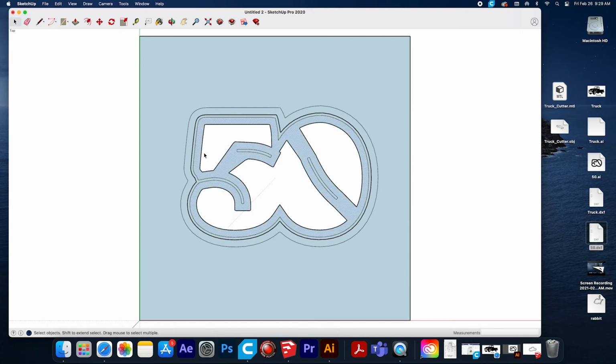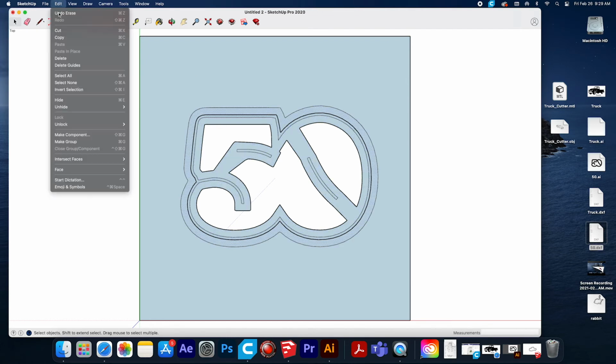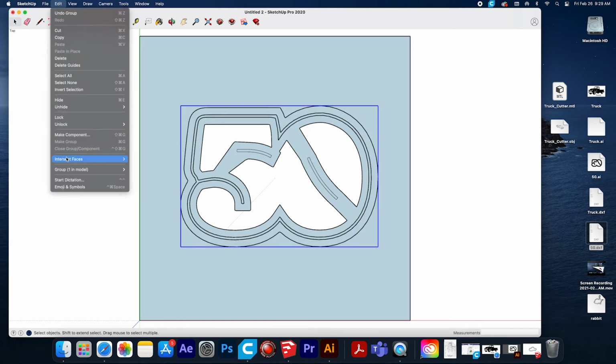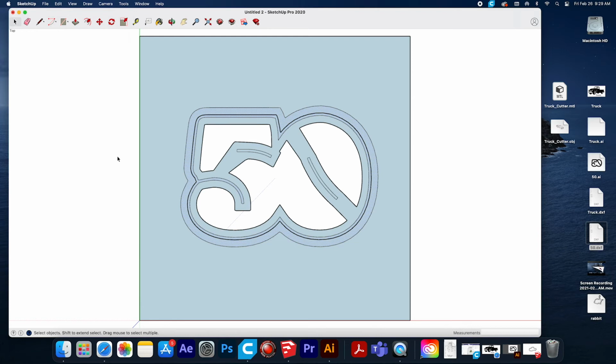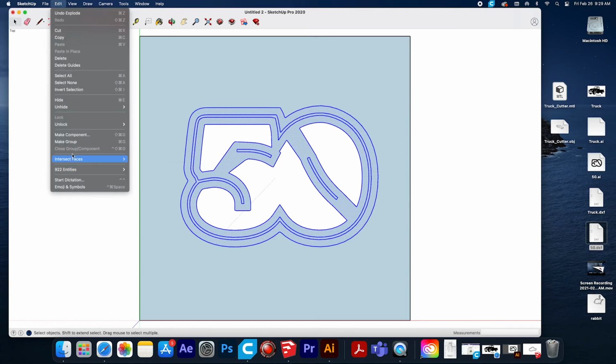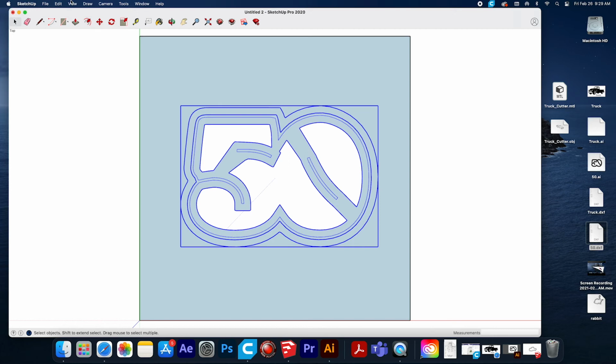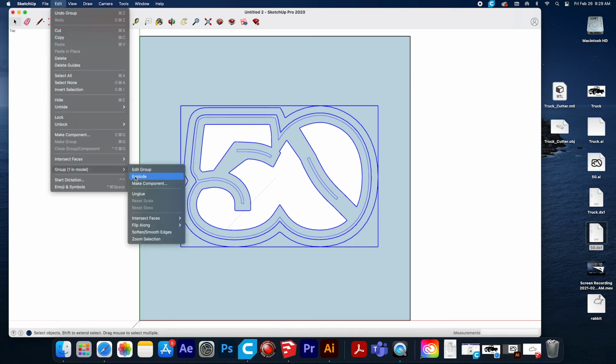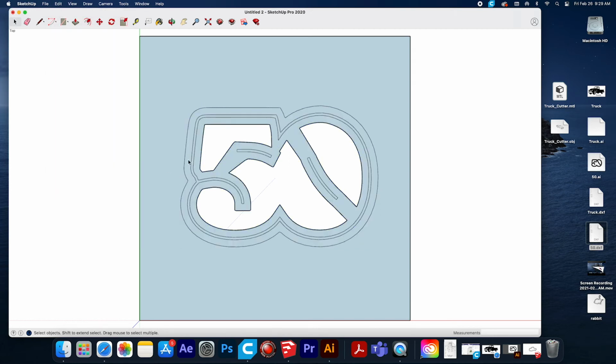No, I don't want to, and that's nice, it's separate. These are still not quite separate, so I'll go edit, make group, edit, group explode, and I still want them all to be separate. So edit, make group, edit, explode. See how we're doing there.